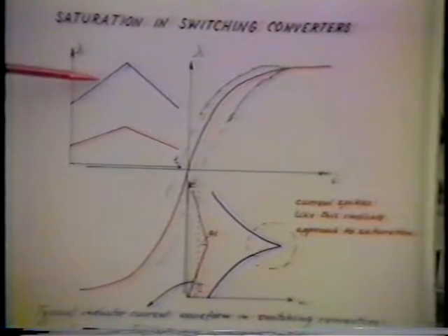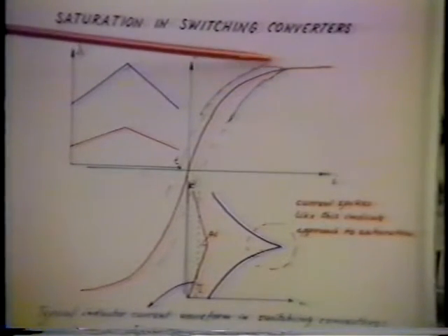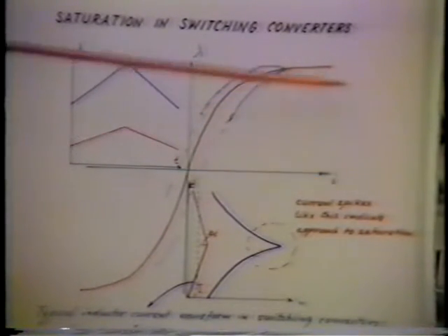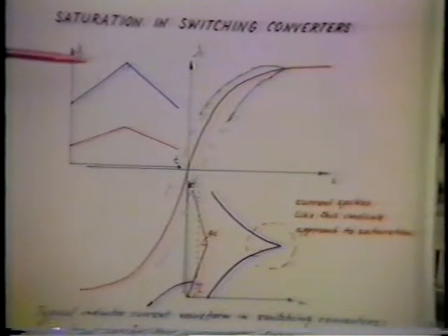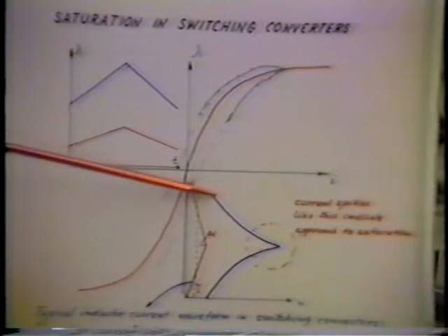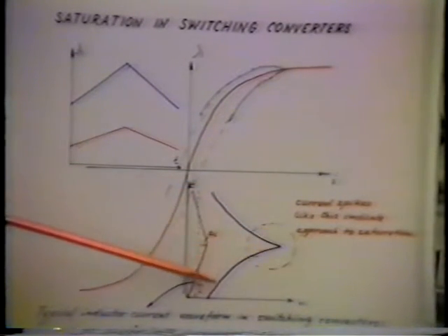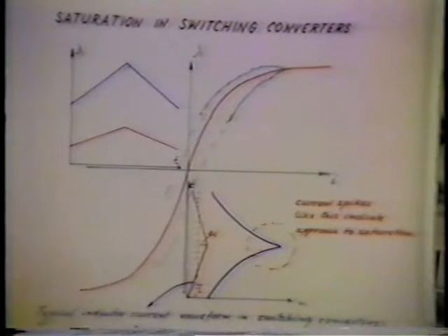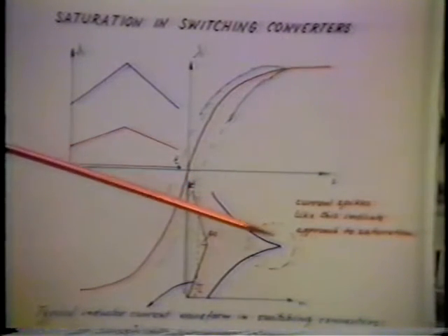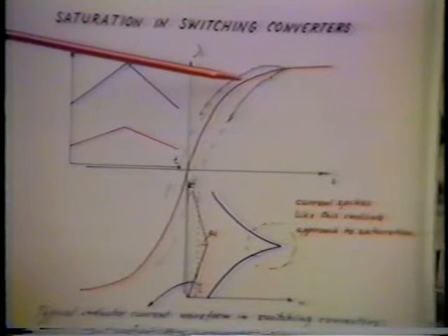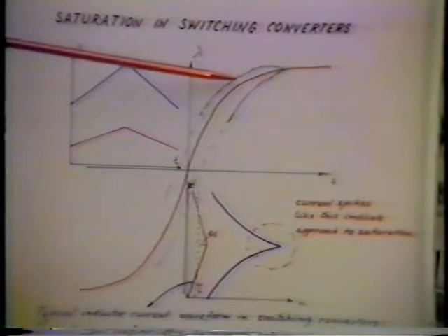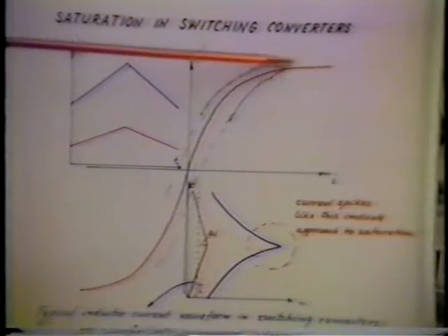However, reflected through the nonlinear flux linkages versus current characteristic shown in red, this will result in the current drawn from the source, or current in the winding, which will be highly nonlinear, and the more so, the higher it is on the knee of this characteristic.